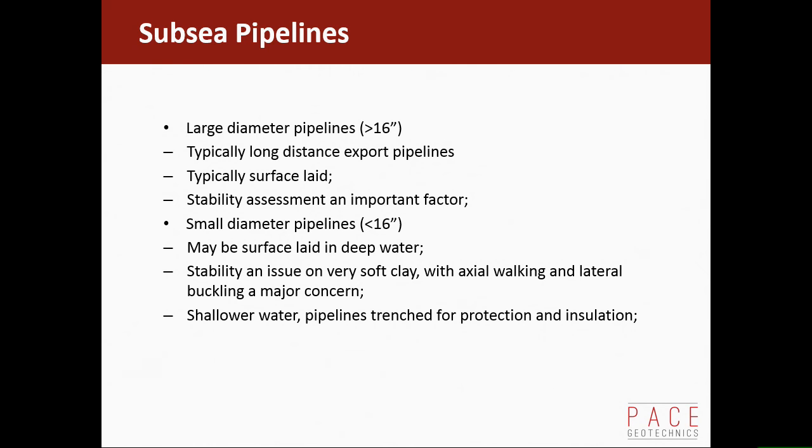Basically the pipeline heats up, cools down, heats up, cools down, so it starts to walk along the seabed. And in some cases it actually generates a buckle. And there's been a lot of work done on that in the last few years. So that's really a deep water soft clays problem.